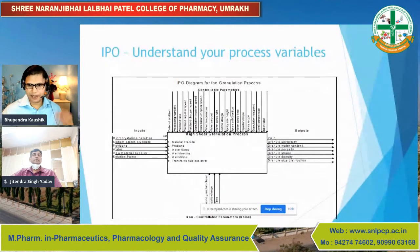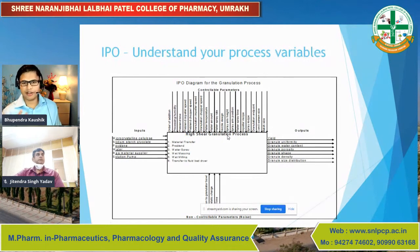For example, simple things like the order of addition of your active in the granulation process can also affect product quality, as simple as that. The amount of water you added, the positioning of the spray nozzle, the length of the spray nozzle, the impeller speed, the chopper speed, and the type of recipe you're using to granulate the product. These are variables that are coming from your process. In the first few slides we saw the variables coming from the active. What we look at in here is the variable that is coming from your process.